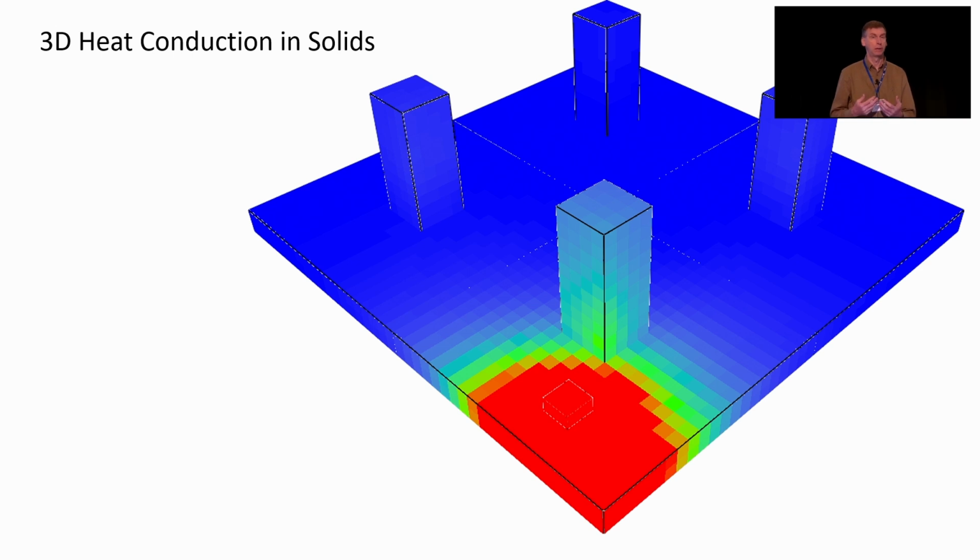The problem with that technique, though, is that it is explicit instead of implicit. Explicit meaning that it has to do with the way the time stepping is done, the way that the temperature in any given grid cell is updated from one time step to the next. And when you have an explicit time step, it means you are constrained in how big your time step can be. And we found that the time step to do these kinds of calculations was going to be smaller than the gas phase time step.